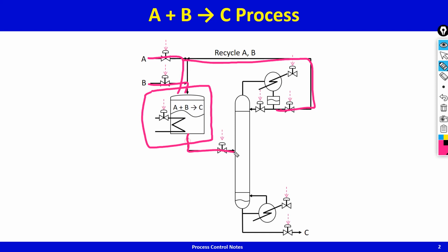And then you're independently setting this guy. Obviously flow out is not likely to be equal to flow in, so the level of this reactor is not going to be stable. Similarly, enthalpy in, enthalpy out, heat being removed and heat being generated due to reaction, this balance will also not be closing, and therefore the reactor temperature will also be drifting, and so on and so forth.